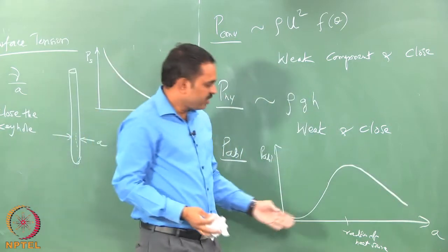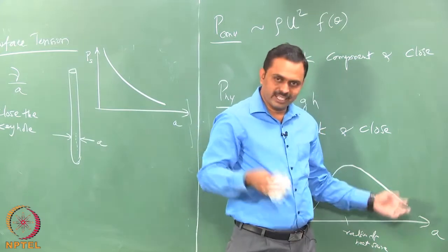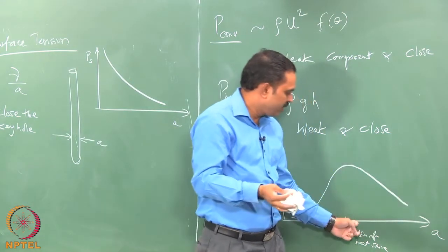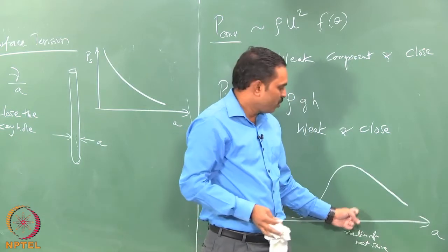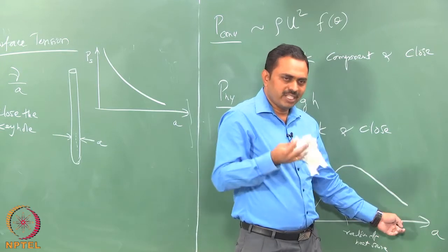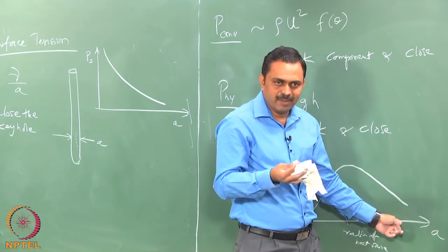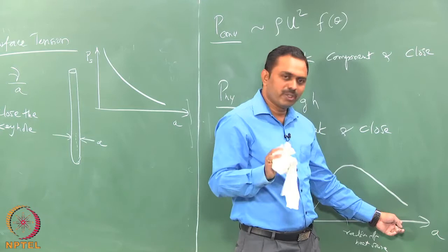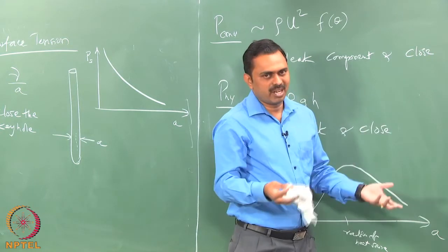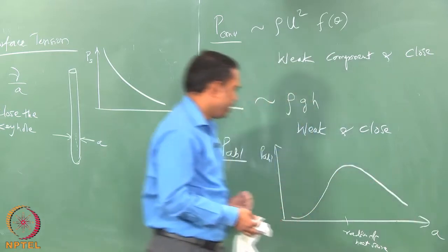Okay. So, imagine a situation where you have a very large keyhole diameter, but the total amount of heat here compared to here is going to be the same. So, the same amount of heat is falling on a larger keyhole, which means that the ablation is happening over a larger area, but the same amount of molecules are coming out of the surface of the vapor column, exerting basically a smaller amount of pressure. So, it is going to go this way.